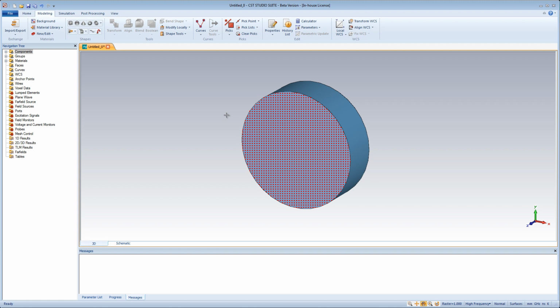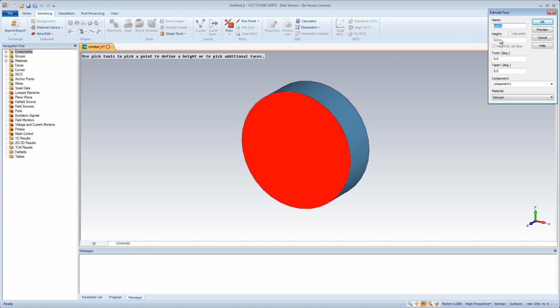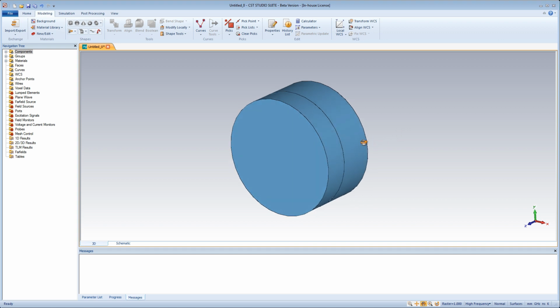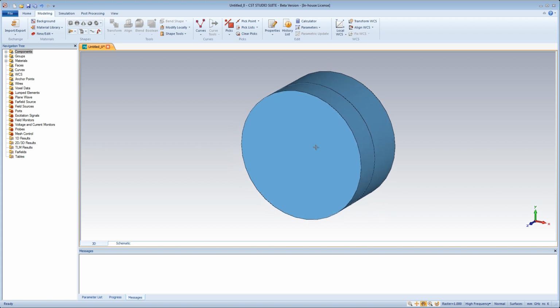Extrude, rotate and loft operations are equally typical construction tools for use on picked faces. In the following, we assume an existing cylinder with a picked top face. Now we can extrude this face by simply setting Shapes, Extrusions, Extrude. When a planar or cylindrical face is picked before this tool is activated, the extrusion refers to the picked face. If no face is picked in advance, an interactive mode will be entered in which you can define polygon points for the extrusion profile. The extrusion tool has created a second shape by the extrusion of the picked face.